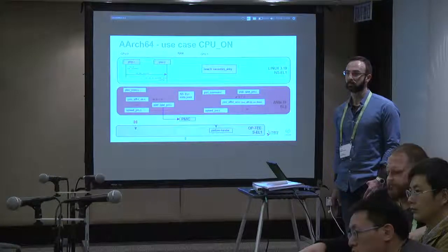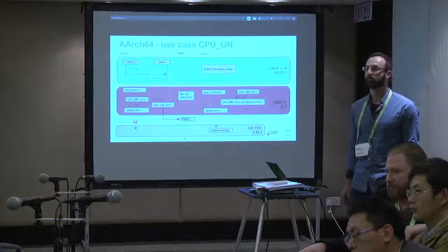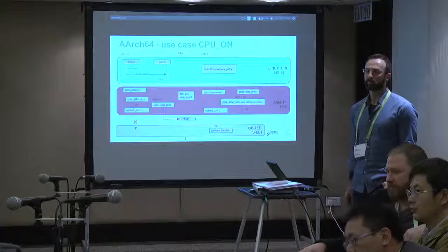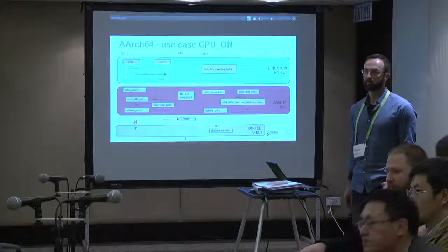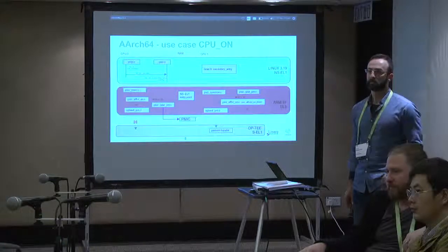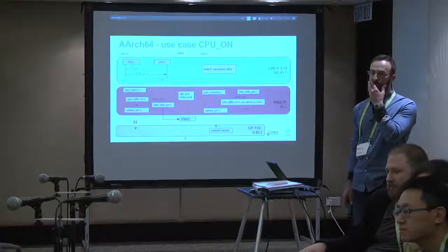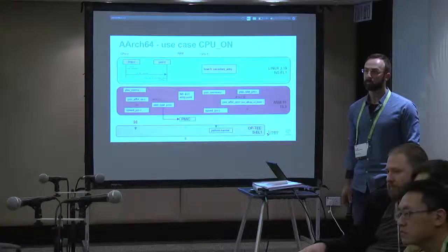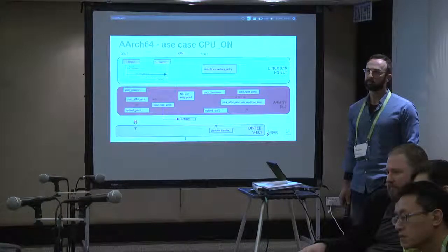So yeah. Previously, what I needed to deal with is a PMIC, which is outside of the SoC. When we want to achieve retention voltage, we talk to this PMIC, and when the APU is going to a low power state, so both CPUs are off, and we'd like to set the retention voltage on the APU, some interaction is performed with the PMIC.